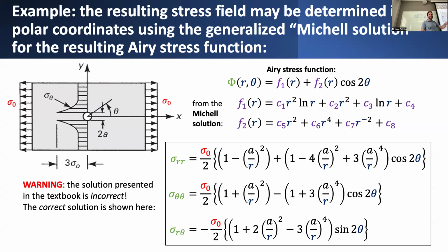But ultimately, you can go through that exercise, assuming you can come up with what the boundary conditions for this problem look like. That requires you to think not necessarily just about what's happening at the boundary of this interior hole, but also what's happening on the boundary of the plate far enough away, which is equivalent to saying, what happens if you take the radial coordinate relative to the center of the plate and look at what happens as r goes off to infinity. That's how you have to enforce these so-called far field boundary conditions.